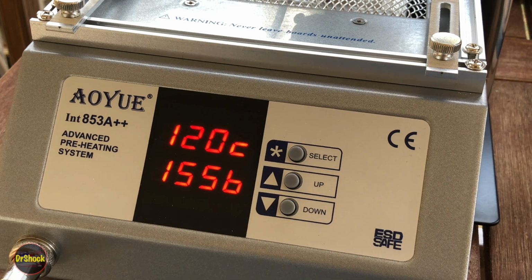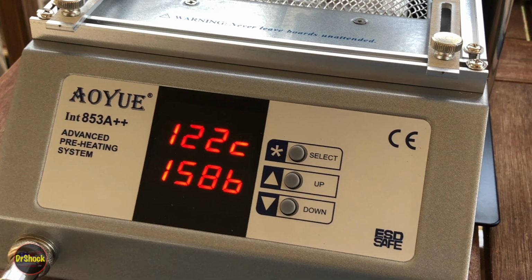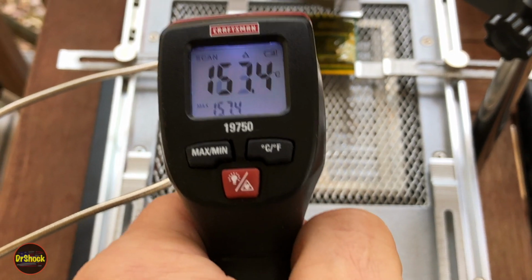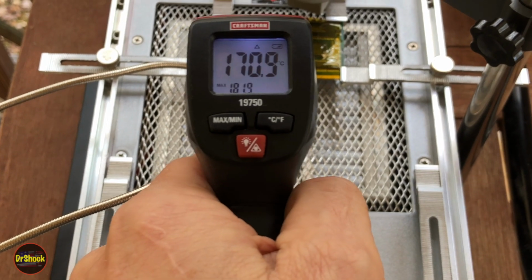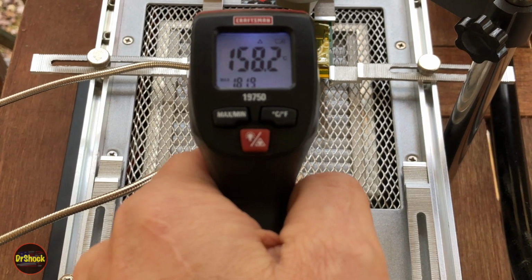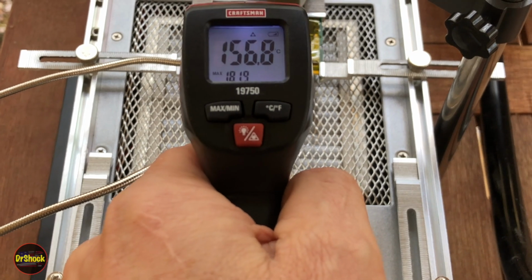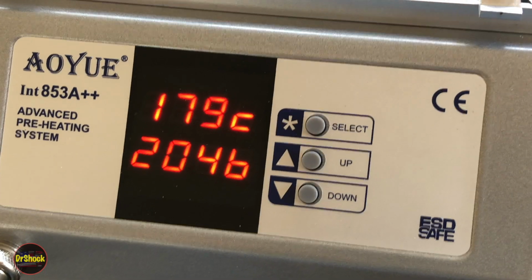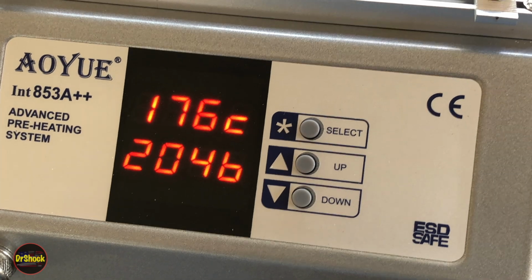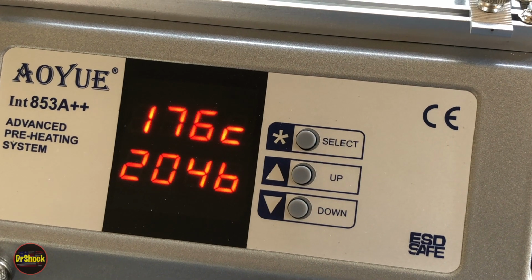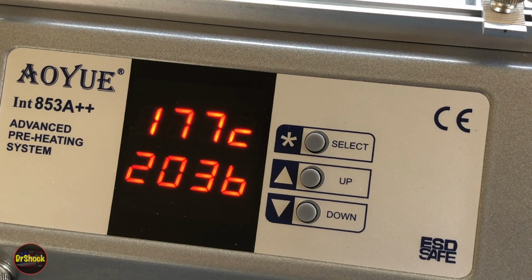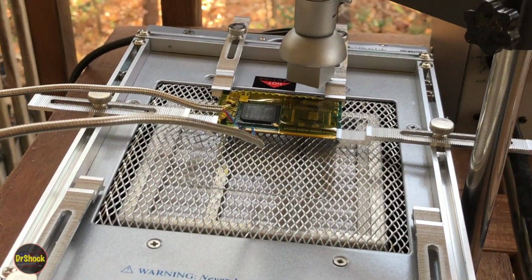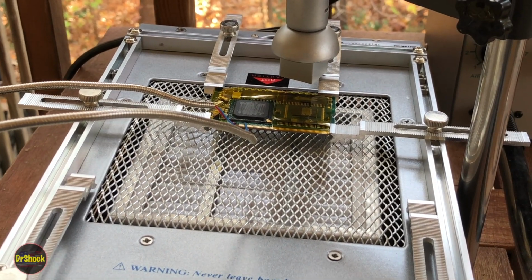So it's going to take it a good 4 or 5 minutes or so to get to where we need it. The secondary check that we'll be doing is we'll be using just a temperature camera like this, just to see what the actual top of the chip is, monitoring it on our way to that 183 soak point. All right, that top temperature is coming up on where we're going to want to move the hot air gun into position, with the nozzle that we've got for this particular size device. I'm going to get that set up and I'm going to move you guys over onto the tripod.